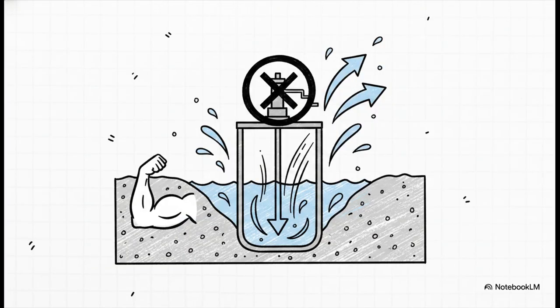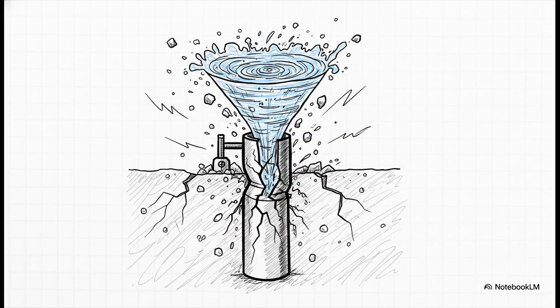So why is stopping the pump so important? Well, measuring those changes after the system shuts off is vital to confirming all that math. A rapid recovery phase proves the underground system has high productivity and storativity. It basically tells the engineers, hey, this aquifer is healthy and can totally handle the stress of continuous pumping. And avoiding overstressing the system is absolutely paramount.